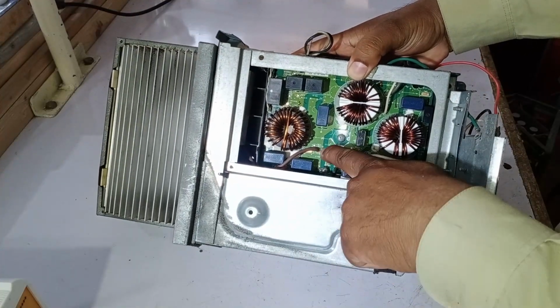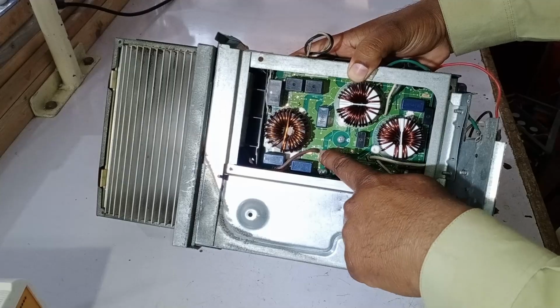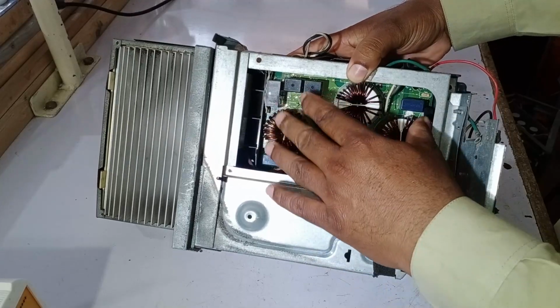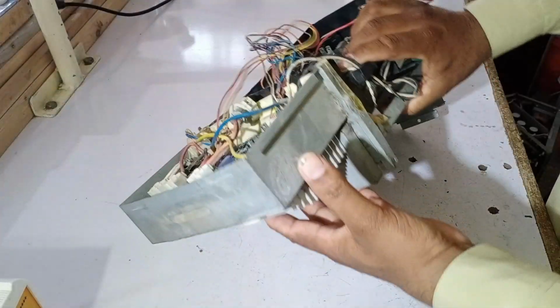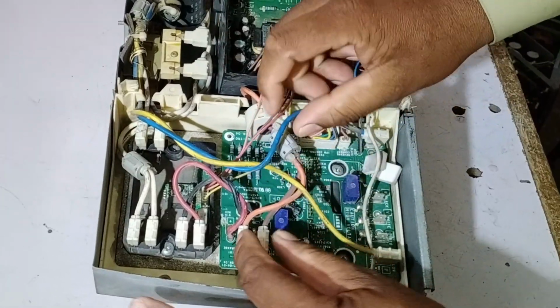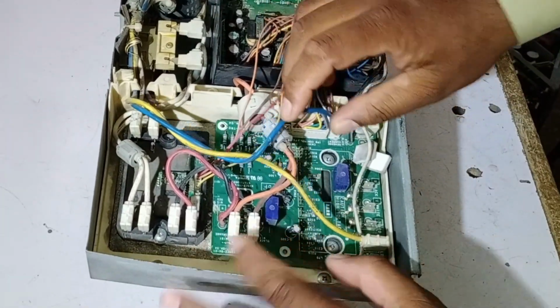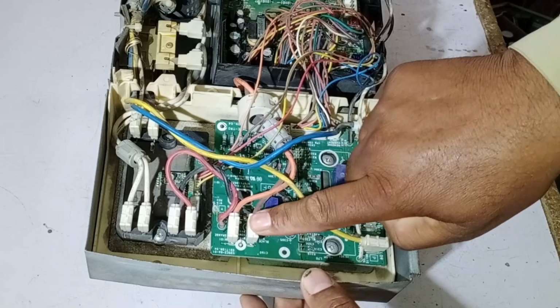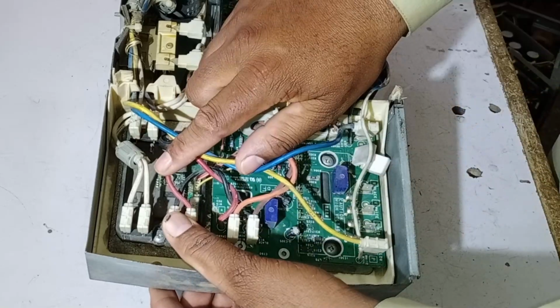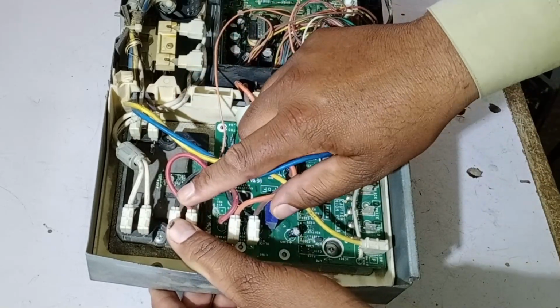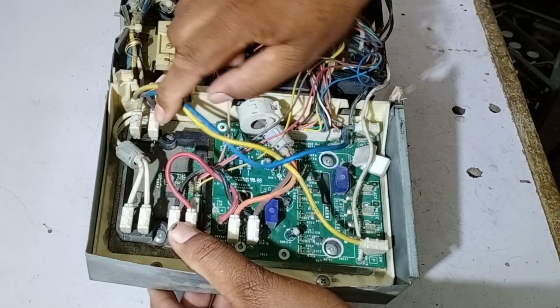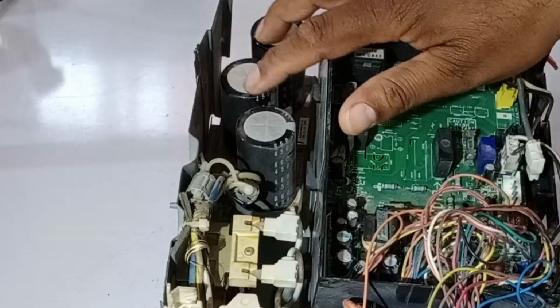If the unit is still not working despite proper wiring, check the power PCB. Electricity flows through the power PCB, and goes straight into the rectification circuit. In rectification, look at these two specific points, red and black wires, which carry power to the active filter module. From the active filter module, the current passes through the reactor and then to the filter capacitors.